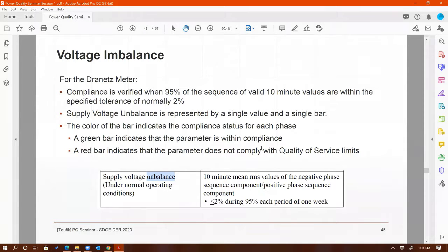AC input, right? And with this curve, I don't have it here, but you can Google it, ITIC. I think they have different names these days. You'll see that there is a range that you have to follow with the IT curve. The y-axis, I believe, is voltage level. The x-axis is the time.